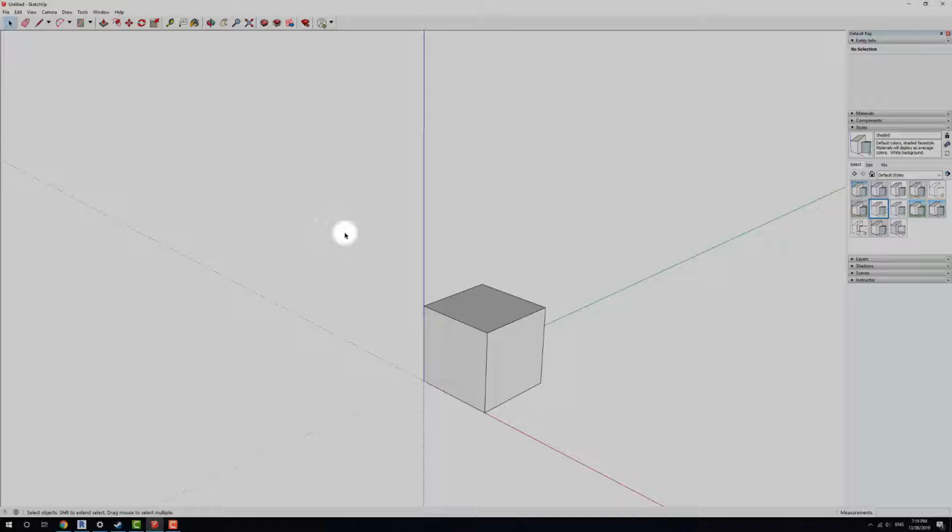Now in order to select it, I'm going to click and drag from the top left down to the bottom right. Notice here I've got a full square out. Now this selection method is only for selecting things that this kind of box encompasses. So if I end it here, you'll notice that this is selected. All right, but we're not selecting this because I did not encompass all of that. So if I click out and drag over it, now I'm encompassing all of the box, and you'll notice it now all gets selected.